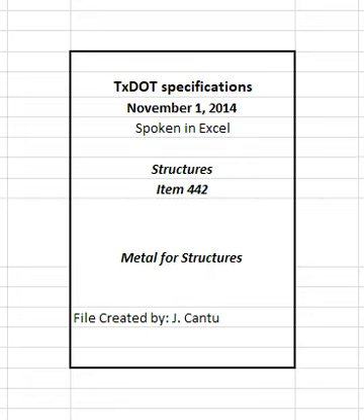1. Reduce the testing temperature by 15 degrees Fahrenheit for each 10 ksi increment or fraction thereof above 65 ksi if the yield point of the material given on the MTR exceeds 65 ksi. 2. Reduce the testing temperature by 15 degrees Fahrenheit for each 10 ksi increment or fraction thereof above 85 ksi if the yield point of the material given on the MTR exceeds 85 ksi.